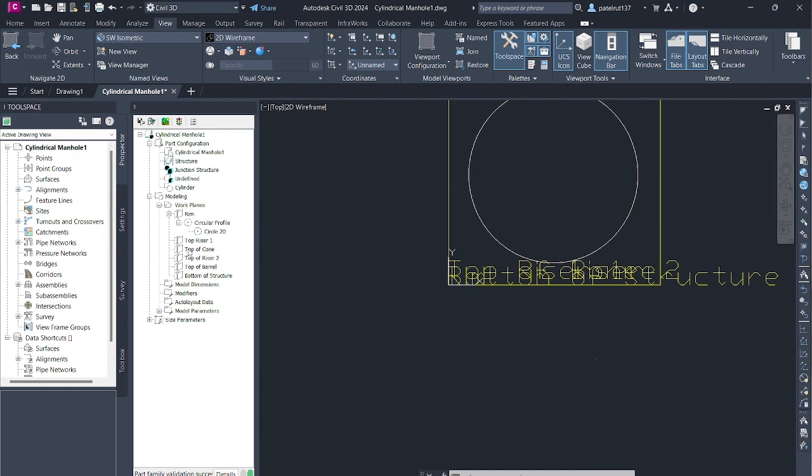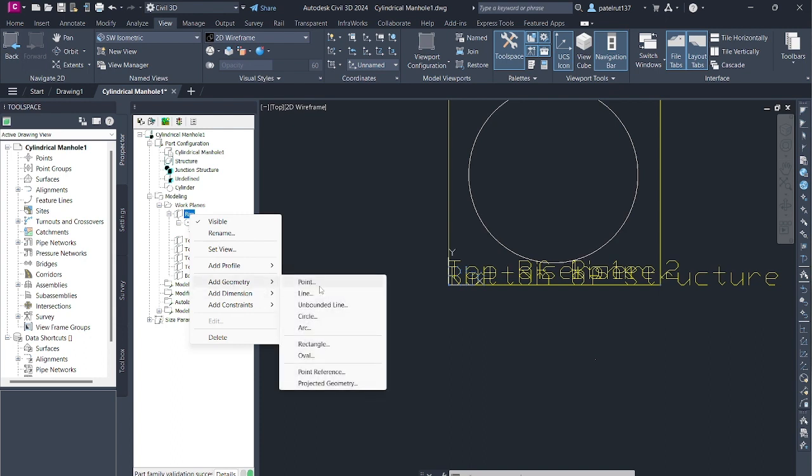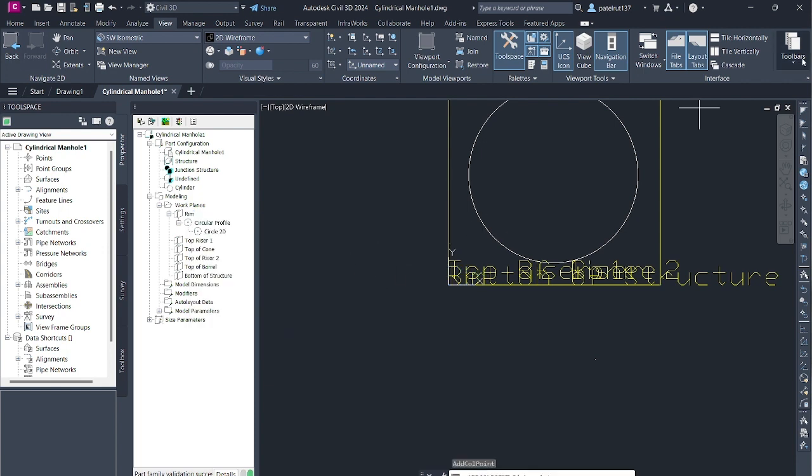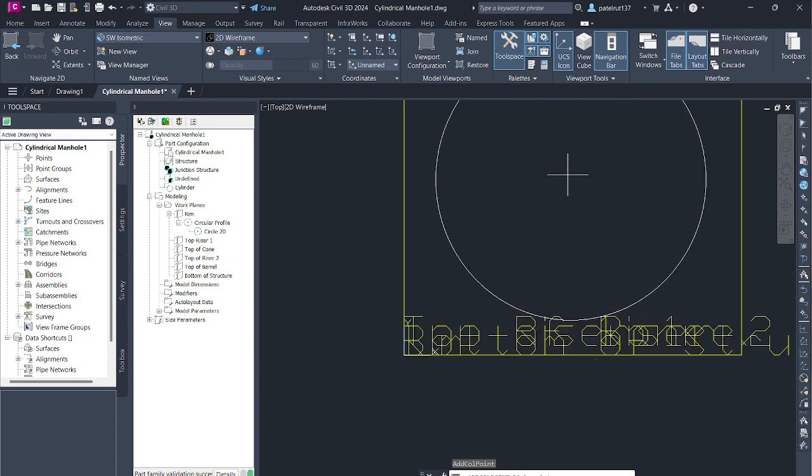The command line asks you to select Offset from work plane. Turn on ORTHO. Select a location approximately 12" lower than the rim work plane in the negative Z direction, and press Enter. In later steps, you will establish a more precise offset by equating these distances with structure parameters. A second work plane is displayed approximately 12" below the first work plane.